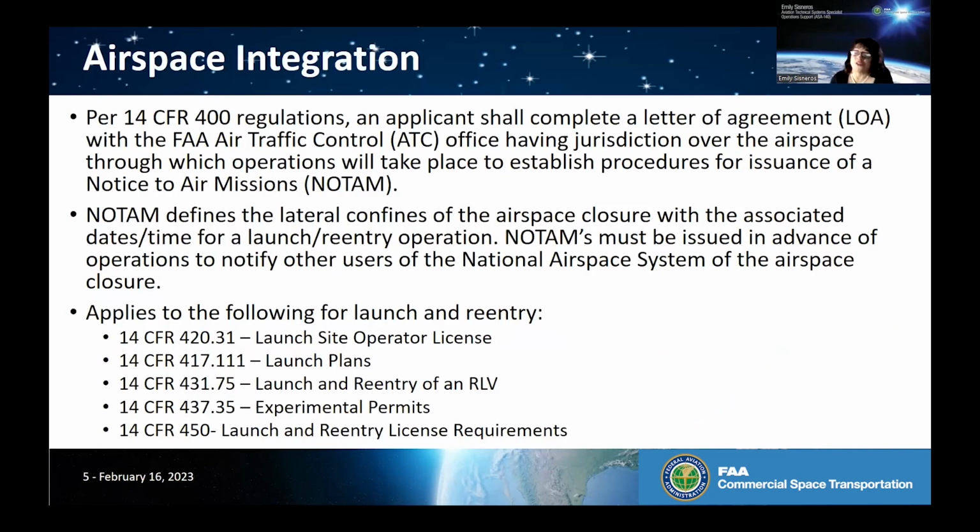So airspace integration, the reason we're all here today. Per our CFR 400 regulations, an applicant must complete a letter of agreement with the FAA Air Traffic Control Office having jurisdiction over the airspace through which their operations will take place. This is to establish procedures for the issuance of a notice to air missions, otherwise known as a NOTAM. A NOTAM defines the lateral confines of the airspace closure with the associated dates and times for a launch or reentry operation. And they must be issued well in advance of operations to notify other users of the National Airspace System of the airspace closure.